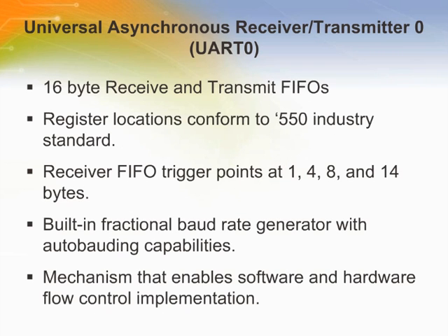The UART0 receiver block, U0RX, monitors the serial input line, RxD0, for valid input. The UART0 RX shift register, U0RSR, accepts valid characters via RxD0.